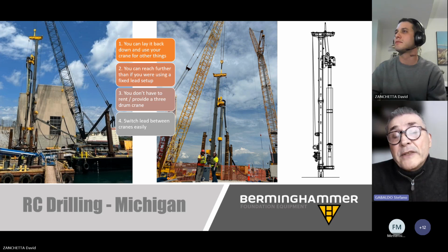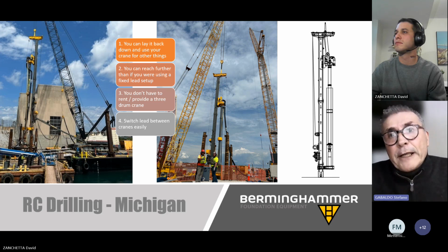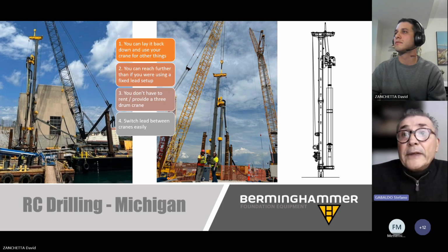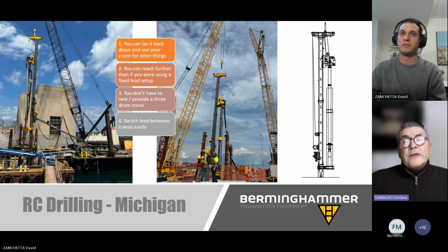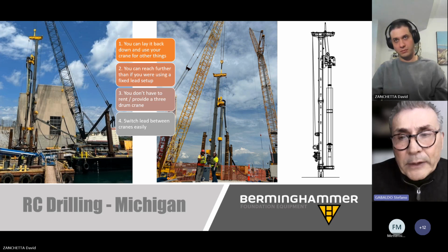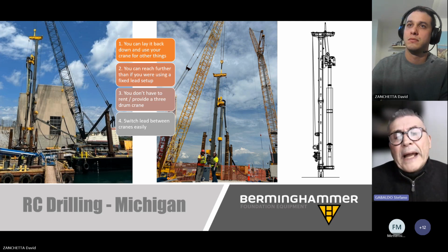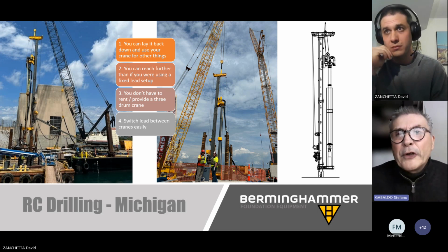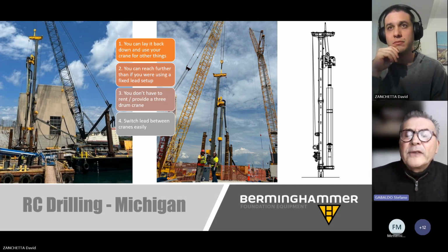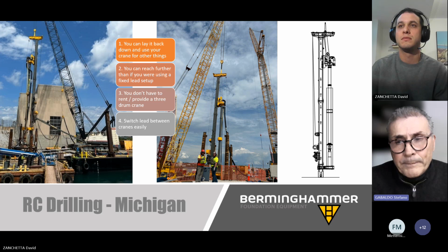One is to minimize the crowd that you put onto your auger as you go down. And sometimes if your verticality becomes crucial, the speed at which you advance the auger will become a little bit slower, because you want to place more importance on the verticality that you want to achieve instead of the production that you can achieve with the system. So I think the bottom line is, once the auger is into Mother Earth, Mother Earth a lot of the time dictates what happens next. In order to avoid that, be very, very careful in the speed at which you advance the system.